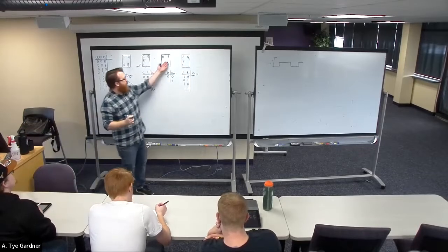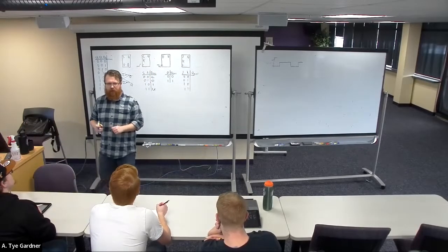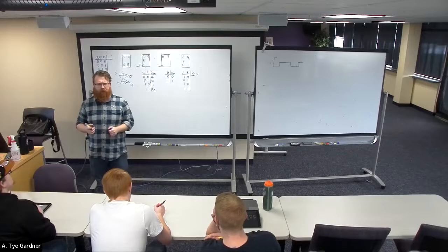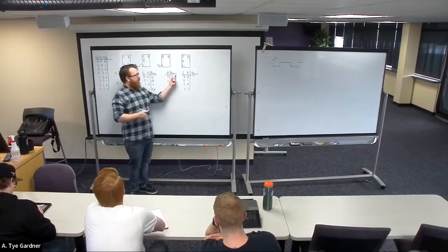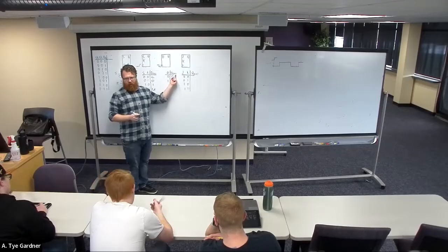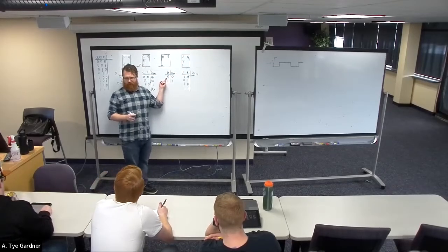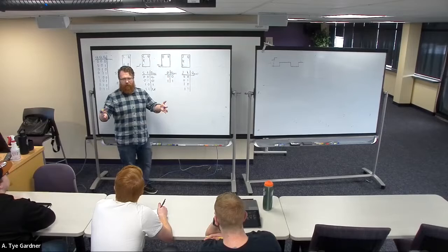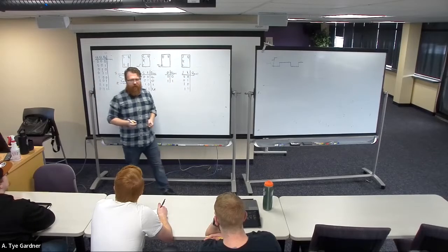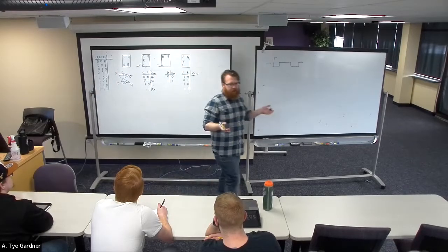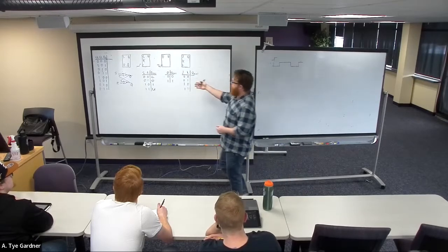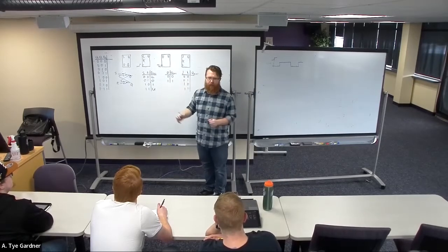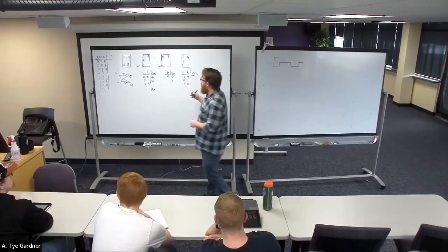Then we can easily build the D flip-flops. D flip-flops are the most prolific, the most common, and also the easiest to use because it simply says at each clock edge, the next Q is whatever the D is. That's all. Whatever data was, let's save it, right? This is basically memory. It's what we would call a register or the beginnings of a register. If I stick multiple of these in parallel and I save many bits, then it's a register. And it remembers what I had.